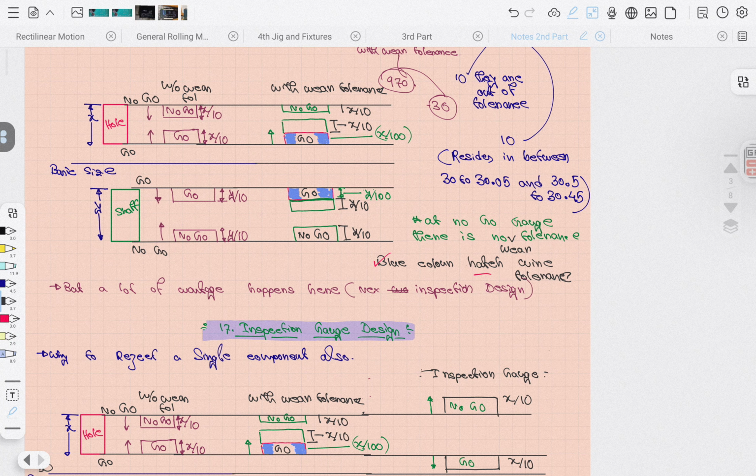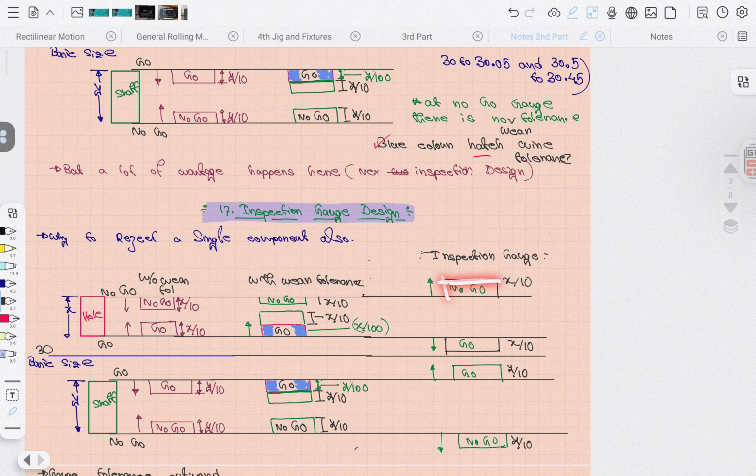There we are a little liberal about the values, how we are taking them, and a little allowable about the tolerance level, because we can take a little extra or a little less. So above you can see there is a minimum material limit, and sometimes we can take less than that, and for the maximum material limit some amount bigger than that can also be taken, there is no problem. But this is possible only in the case of inspection gauges. In other cases this is very difficult and out of the rule that we have been given. So it's simple that you need to remember.